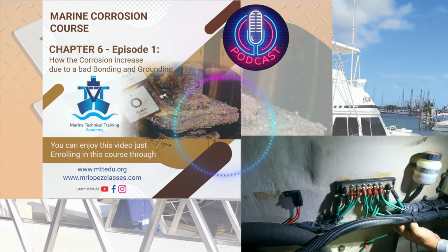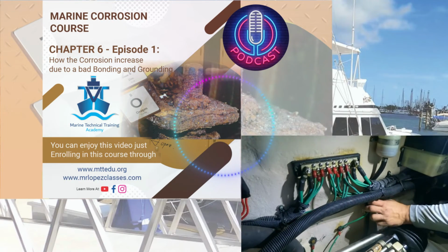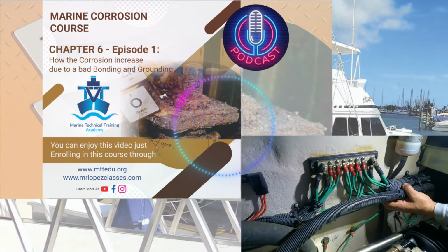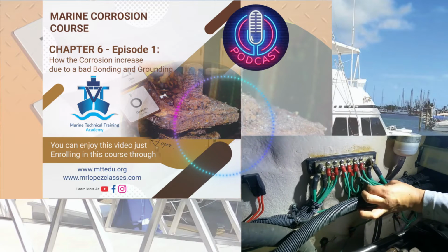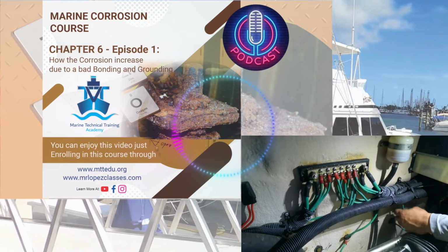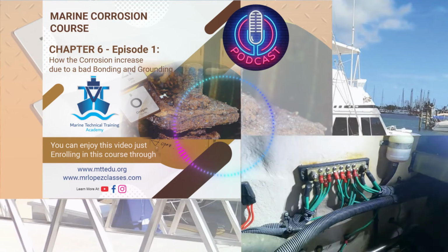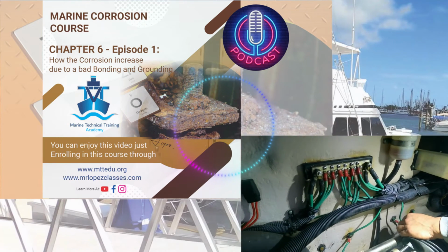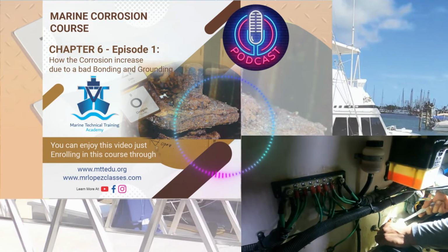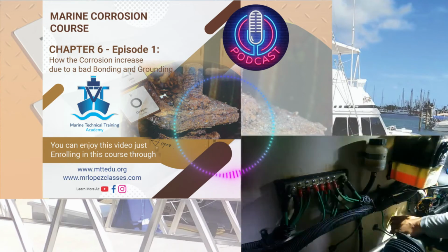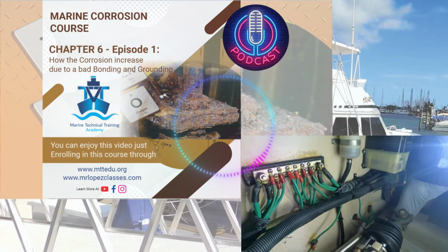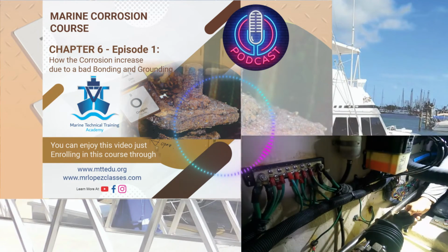What happens if for some reason there is a short to ground internally in the appliance? What is the meaning of that? In one moment, suddenly the hot touches the case. 120 volts touch the case. What happens with that excess of current? It's drained here. For that reason, the gauge of this wire is enough to support big currents in an emergency. Or during lightning, during storms, high voltage, millions of volts, can be drained through this cable, goes into the sink and is dissipated in the water.